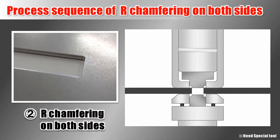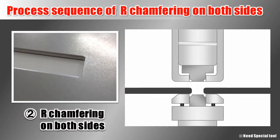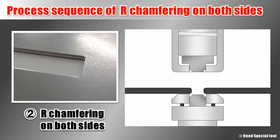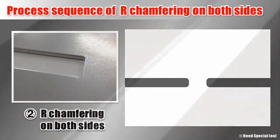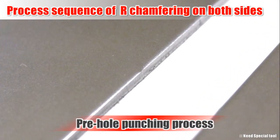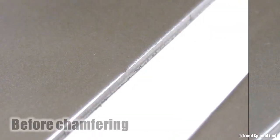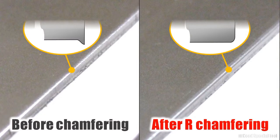Second process is the R chamfering on both sides. Round shape is formed by progressive feeding process, so the process length can be set freely. Here we use the tool to feed at 18 mm pitch. Pre-holes can be done by punching as well. The overlap marks and burrs from this process can also be round chamfered.